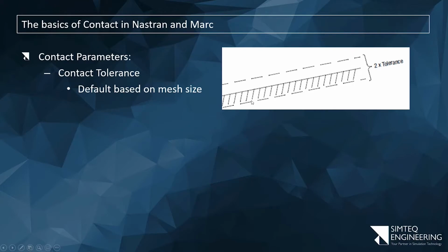Now this dashed section there is the inside of the part. So this is the solid, and where there's no dashes, that's the air. And that distance tolerance, there's a second parameter that influences this. But if that parameter was 0, it means whatever the distance tolerance or contact tolerance is on the outside, the same on the inside. So the total checking region is twice the tolerance.